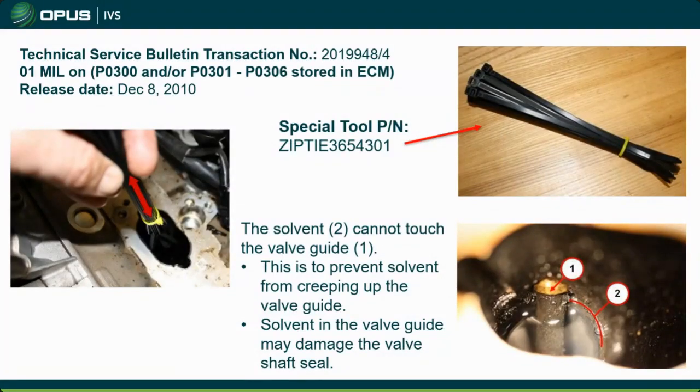I would say one of the major things that we have when these things fail is excessive carbon buildup. I mean, really bad carbon, enough to hold valves open, enough to cause scoring on cylinders, enough to affect the compression ratio in your engine. These things can really build up depending on a lot of things, but mostly on lack of service, lack of using good oil, and a lot of short trip driving.